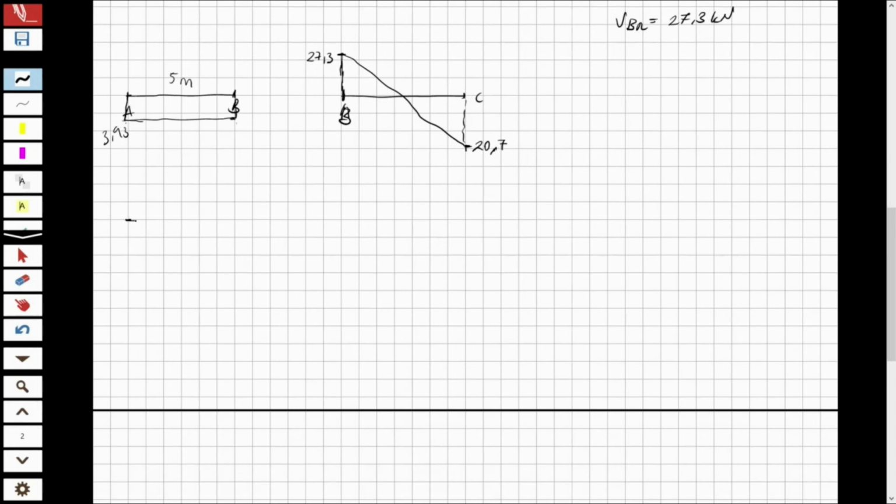And now let's draw the moment diagrams for both. So the moment diagram will be something like that. Now you can see there is no moment here, so I'm going to start with 0. And the moment will be the amount of this area. It is downward, so I'm going to read down. What is this amount of area? That will be 19.6. So for the next part, I am going to start with 19.6. It is still at the bottom, so I'm going to go on with the bottom.